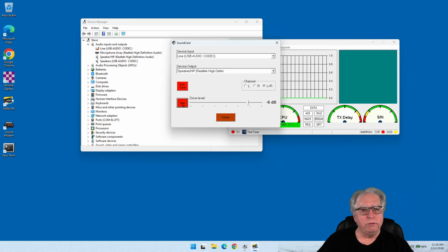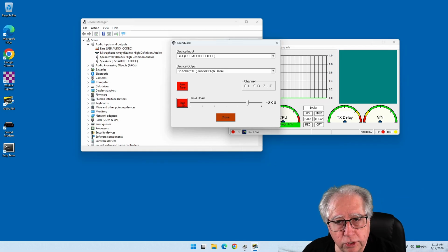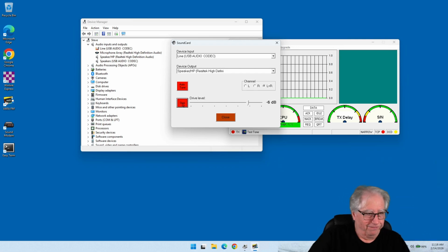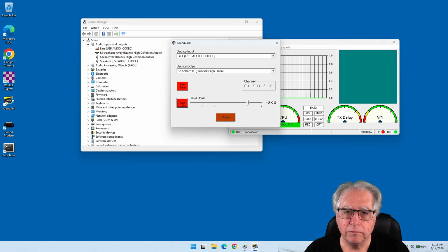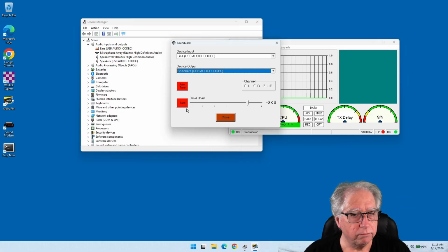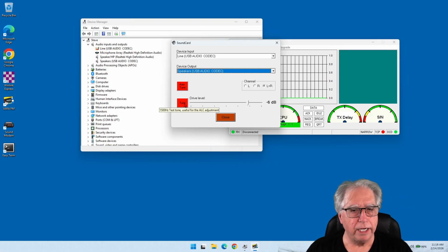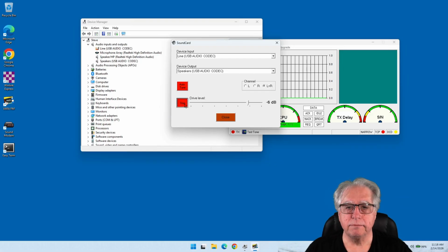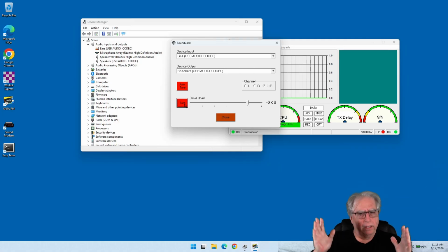So I can hit tune, and I can reach over and turn off the radio on the receive side, but I'm still hearing the noise. Well, there you go. That implies that it's wrong. How do I know that it's coming out the right port? Well, I have the radio turned down, I hit tune, then I bring the volume up on the radio. There it is. Okay? Very simple, but you verified now that your transmit is working.